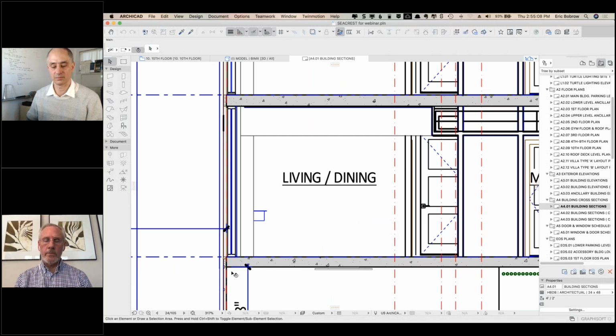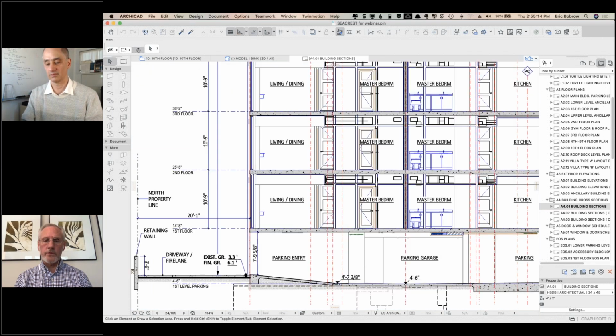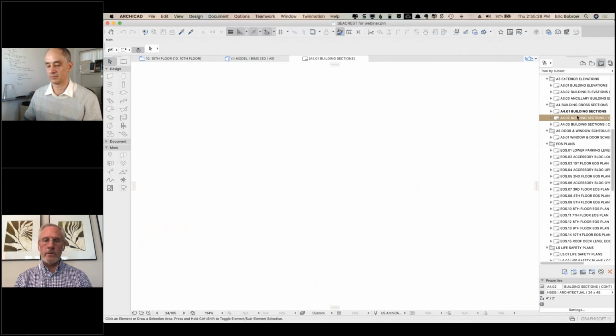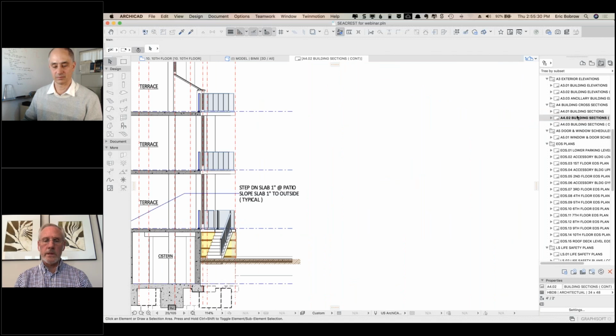I've been doing the mechanical off of the mechanical consultant's drawings just to make sure. I don't think they're modeling everything in 3D. They work in Revit, but mostly AutoCAD, I think. And they're doing the MEP and F in this project, but I want to make sure that we have enough room in our drop ceilings to carry all that without problem. So I'm going to model it out myself, and then we'll have meetings with them.